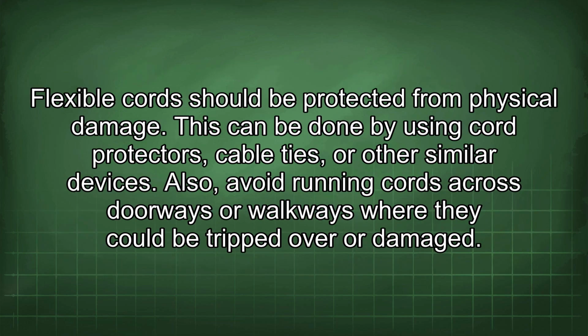Flexible cords should be protected from physical damage. This can be done by using cord protectors, cable ties, or other similar devices. Also, avoid running cords across doorways or walkways where they could be tripped over or damaged.